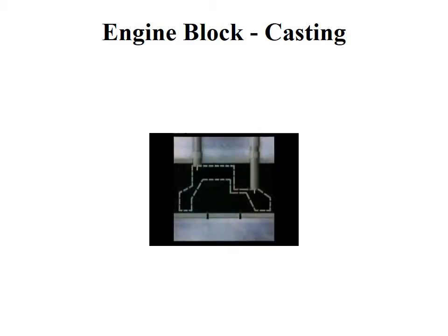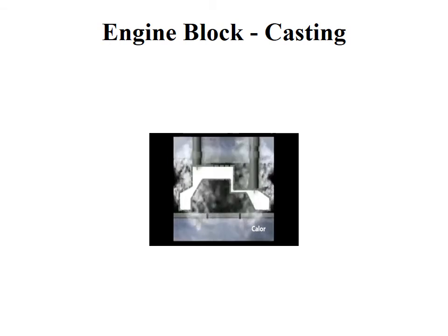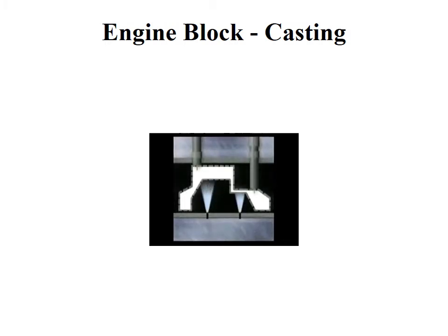The preheated cavity is completely filled with beads through fill guns. Steam is again used for heat and now enters the cavity through vents and further heats the tool from the back side. This causes the beads to expand into the voids and to fuse together. The fused foam and the tool are cooled by water and vacuum to allow the foam to be removed from